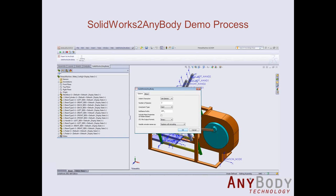You can choose which character should be used for the indentation of the resultant AnyScript files, and you can choose how the mates in the assembly are converted into AnyScript, either hard or soft constraint types. Also, if you use some prefix for the names of reference coordinate system objects, then SolidWorks2AnyBody will generate references of those AnyRefNode objects from the reference coordinate systems in your SolidWorks model. And you can determine whether to include mesh properties or hidden bodies in a component or not.